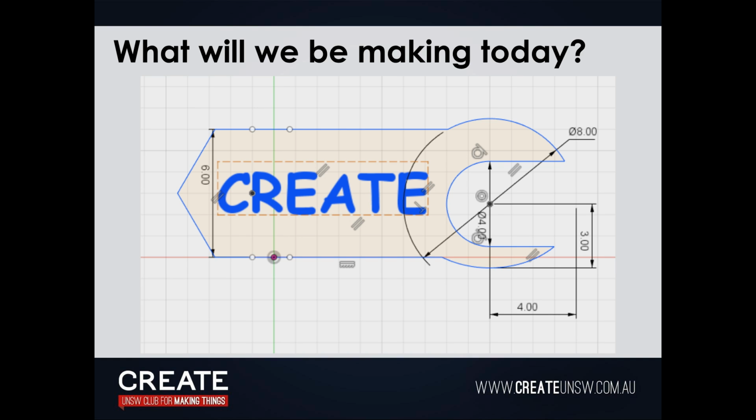Next, what you want to do is you grab your circle, center diameter circle. You put that in the center, which is right there. It will snap to it. When you notice something is in the center, it will have this triangle, as you can see. Now, that doesn't really matter too much. Actually, we'll do an arc. It might make life a bit easier. We'll do a 3-point arc. So that, and that right there. Okay.